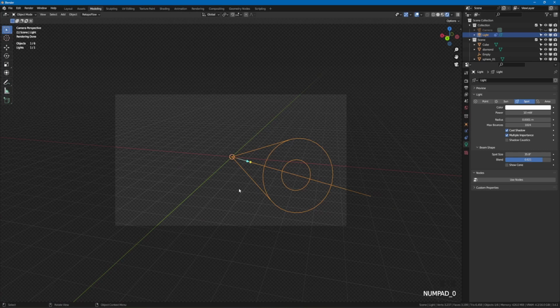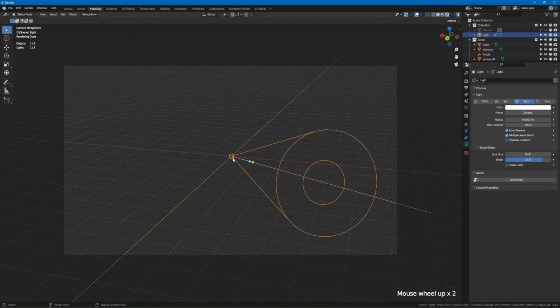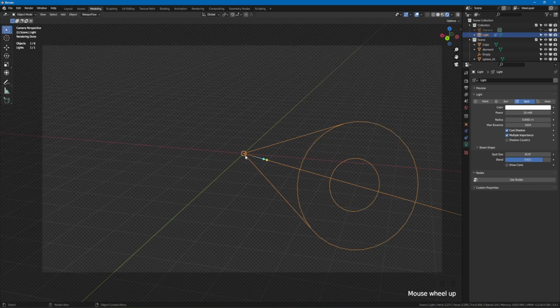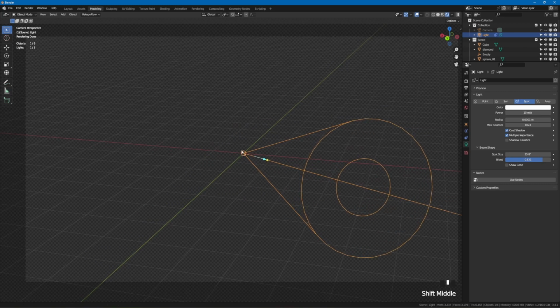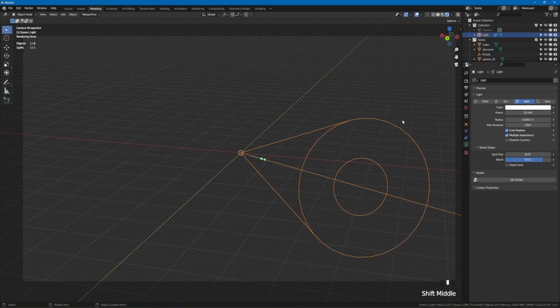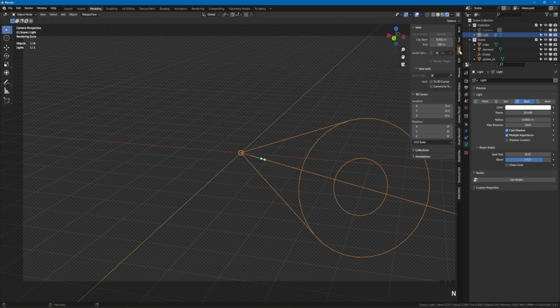Now we set what we want to see when rendering. Press the 0 key on the numeric keypad and scale the gray frame until it fills the screen. Then press the N key again, View, and activate Camera to View. The frame is now fixed and the scene can be adjusted. With the F12 key we make a test rendering.